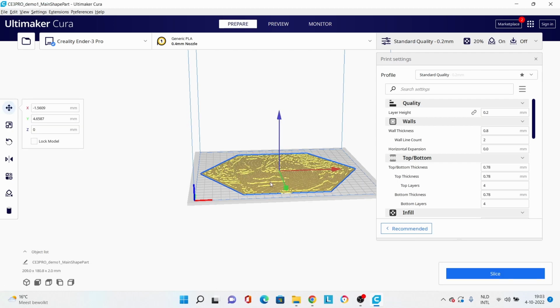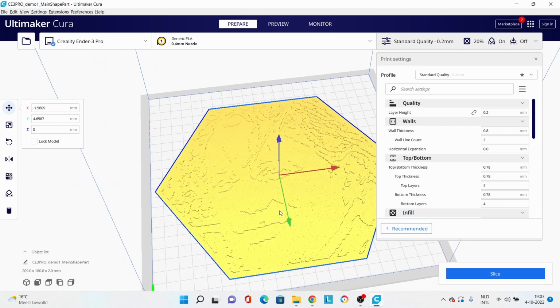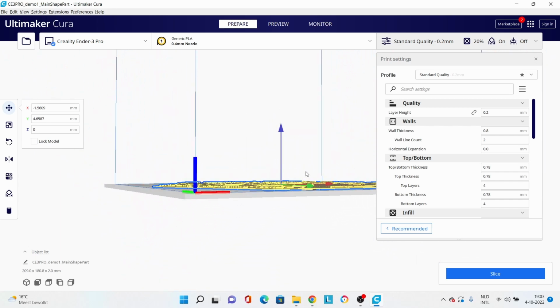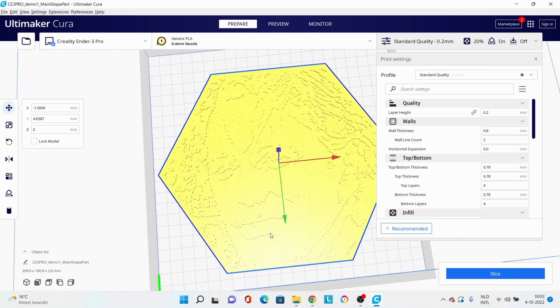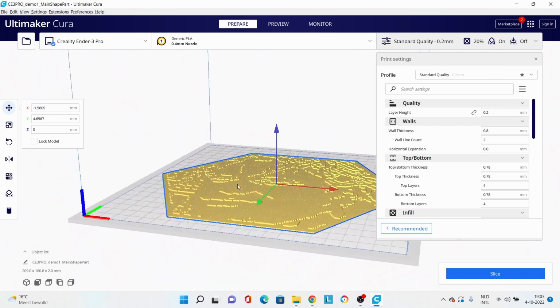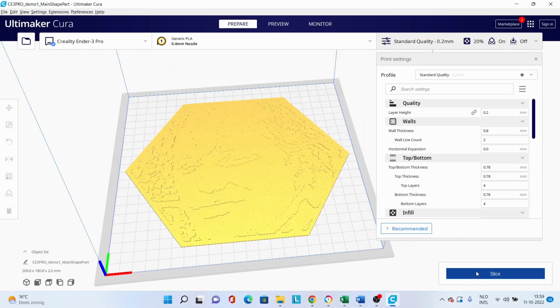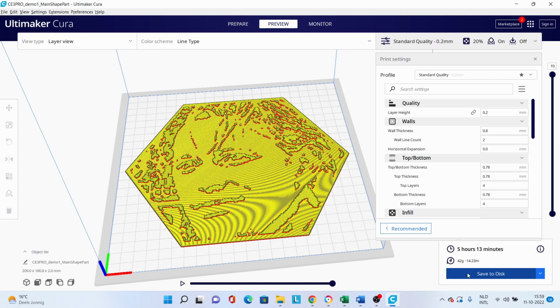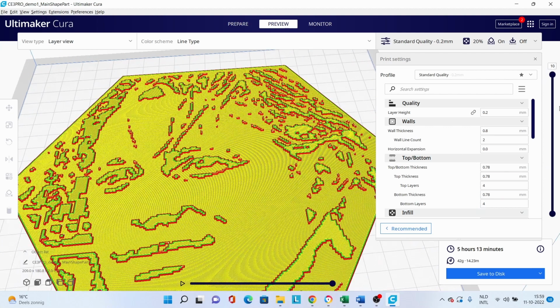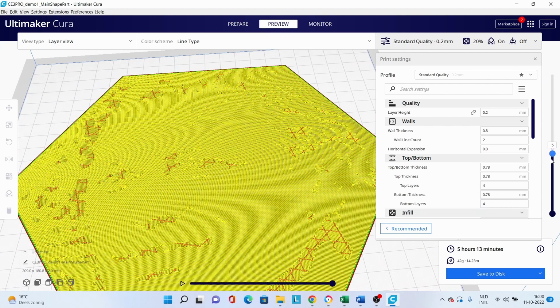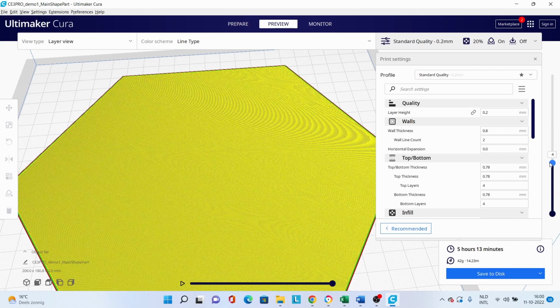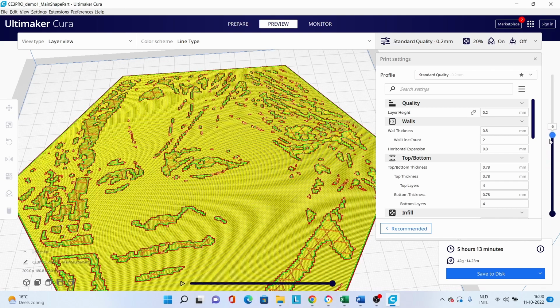In this example, we use Ultimaker Cura, but you can use any slicer you want. It is important to search for the transition between the layers, which is also indicated in the instruction file. This transition is the exact point where you want to pause your printer. When the printer is paused, you can change your filament to a different color.